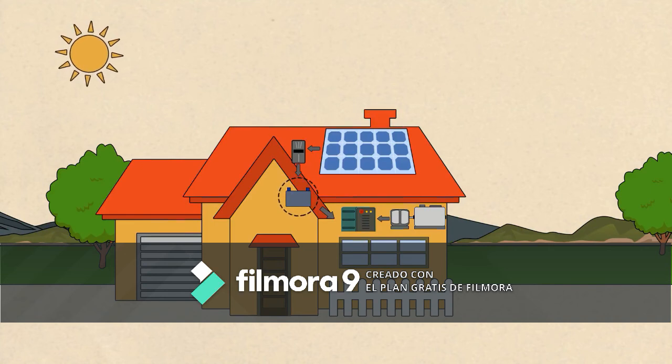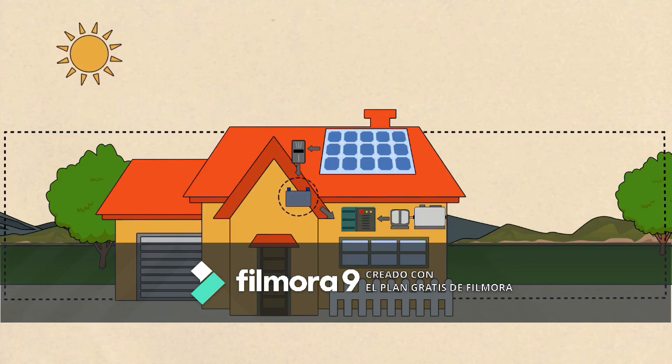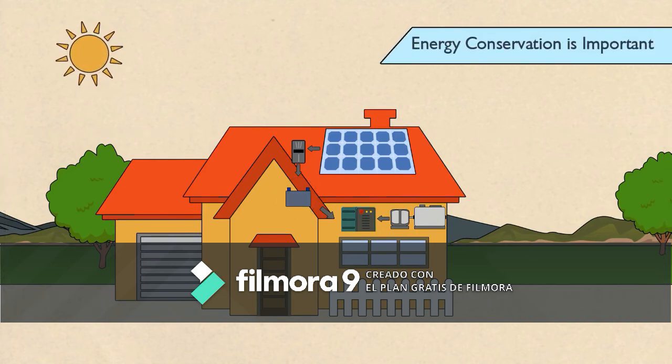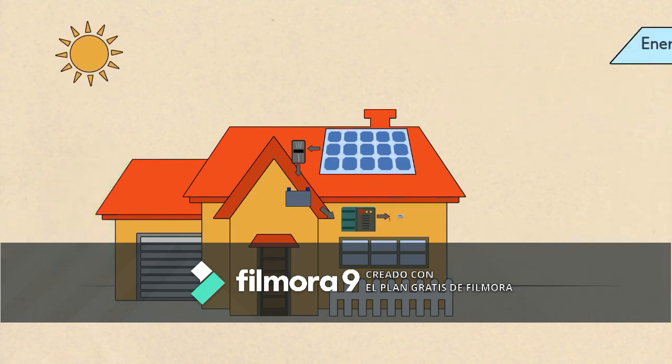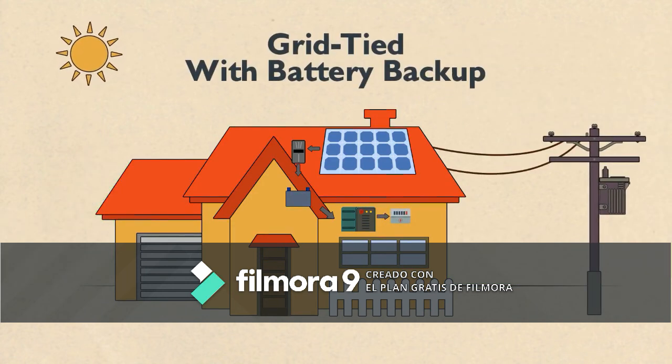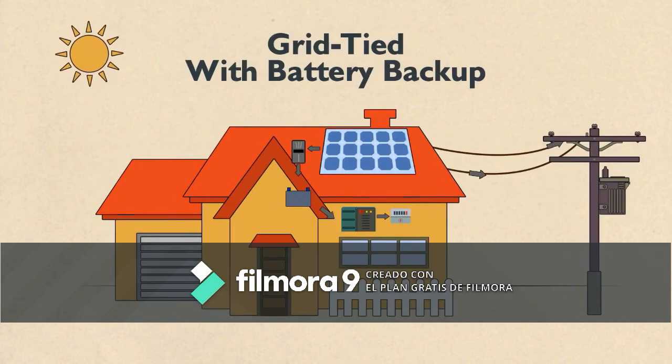These have a higher system cost because of the addition of the batteries, but can also let you access more affordable land. With an off-grid system, energy conservation is important, so energy-efficient appliances and a backup generator are essential. The best of both worlds is a grid-tied system with battery backup, which is ideal for anyone with unreliable power and critical appliances, like a water pump, lights, or security system. It's also more expensive than a standard grid-tied system and has lower return on investment. With this system, the solar panels send power into the grid for credit when it's available, and batteries power some appliances during an emergency outage.